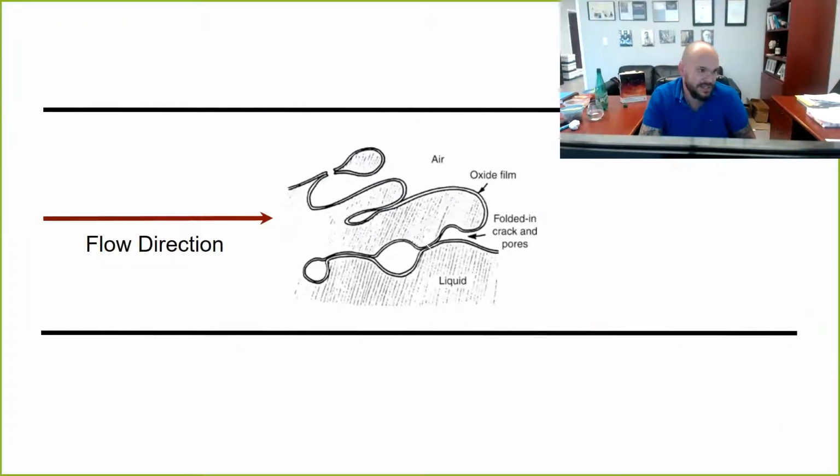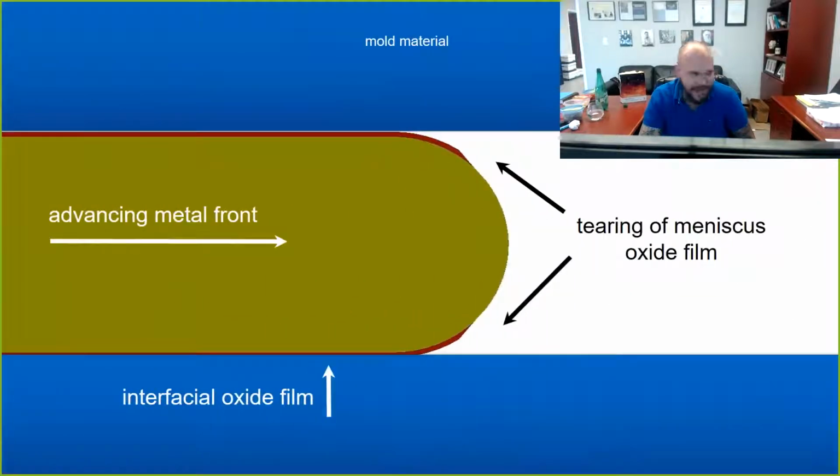Here's what happens in the runner that's not full. Metal is hopping, skipping, and jumping, rolling oxides and air films into it, producing a disgusting pudding. This is what we want to happen if we design using geometric constraint.